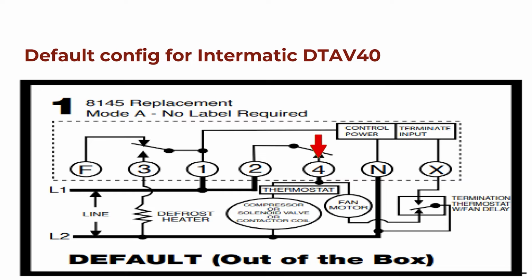And also to the fan motor, we have terminal N here, which is bringing in our other line side of our circuits. Well, in this circuit, it looks like it could be a 240 volt circuit. Line 2 is coming in and terminating on N. Now this could confuse electricians who are used to using neutral. You look at N and say neutral, but you could sort of look at that the same way.